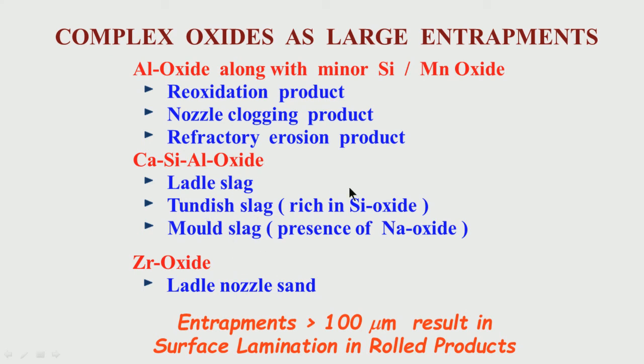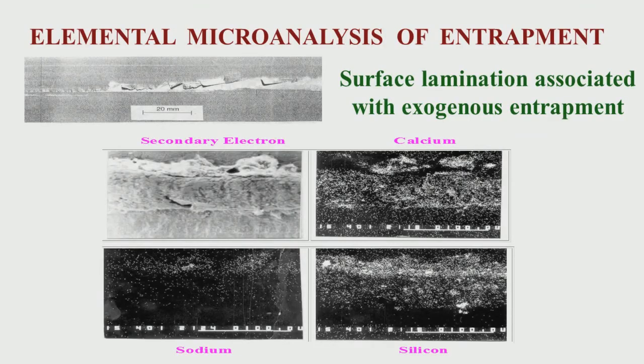You can also know by analyzing the defect samples, that also I have mentioned. If you have a defect, just under the defect whether any entrapment is there, whether any exogenous entrapment is present. Such large defects, there is a possibility of having some entrapment. So, we should know where the entrapment is coming from, what are the sources of entrapments, what is the genesis of entrapments.